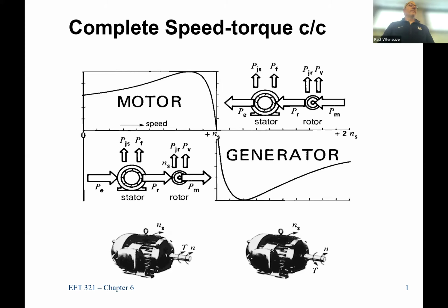We're thinking about the generator, right? Yeah, you still need, so remember what we said, on an induction machine your voltage has to be externally supplied. If you don't have any external voltage, then you're right, you can never get the system started. But you have that external voltage so that you get that magnetic field on the stator and on the rotor. Once those two exist, then you spin it and now you've got a voltage. So you need that voltage to provide the magnetic field. That's ELI the ICE, right? You need a voltage there to be able to provide the magnetic field.